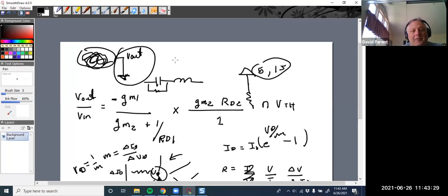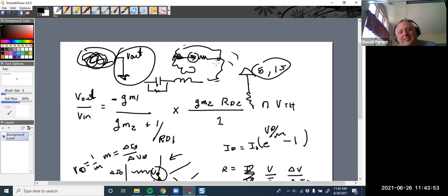Or I've seen all these complicated circuits, and then somewhere in between, there's a current source and a resistor. So there's all this distraction, and they'll ask you, what's the current through the resistor? Well, it's one branch, it's whatever that is. All these devices you've never seen before, doesn't matter. That's a current source and a resistor. It doesn't even matter what the device is. Ideally, it would push that current through no matter what.